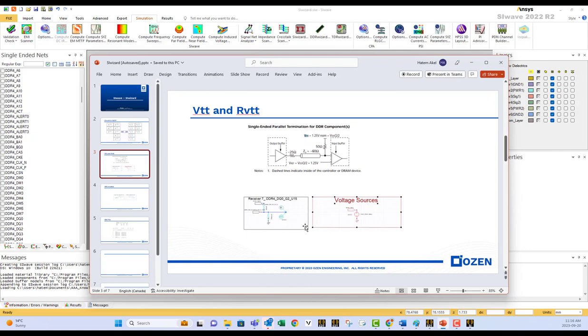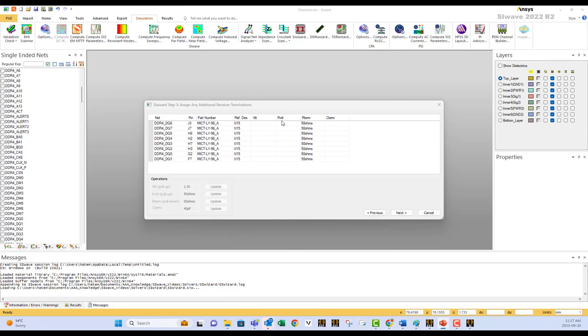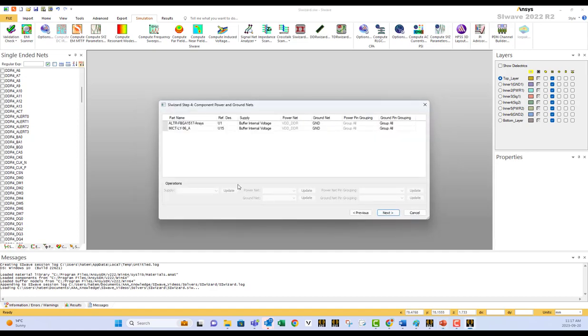And if you do that and you go and you create the schematic, Signal Integrity Wizard will create this pull-up resistor and will add the voltage to it. That's the purpose of these two columns. Of course, here, like you have a termination for the resistor, you could also have a parallel capacitor for the termination on the receiver. If we are satisfied, we go next.